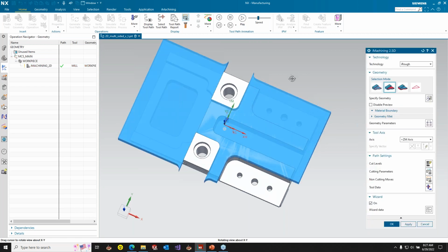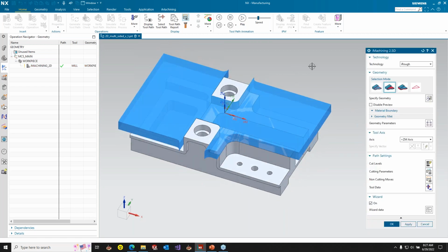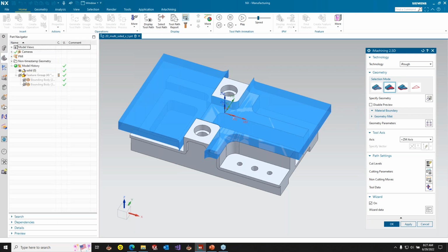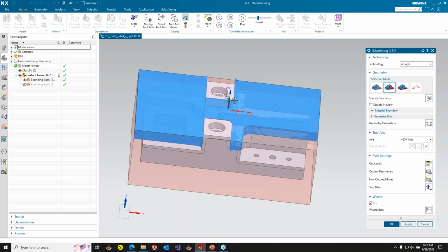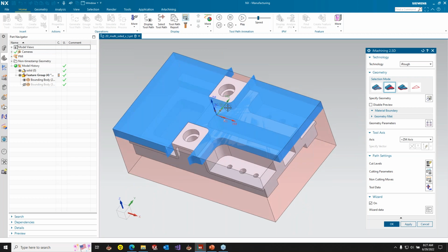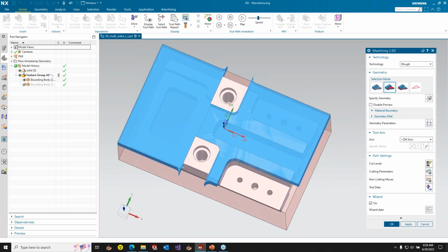And this is a really awesome example to show how powerful this technology is. So if we look at this blue region, we can see what the feature recognition code did and how this got modified and extended and adapted to the stock and the target. So if we go back and look at our stock, we can kind of see what went on. So we want to machine this pocket, right? So we pick this face. Well, with that face, we have walls, but then it's just an open pocket. Like all the other edges and stuff are all machined out to like air.